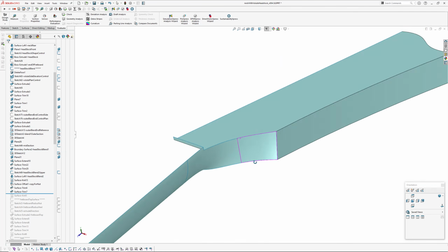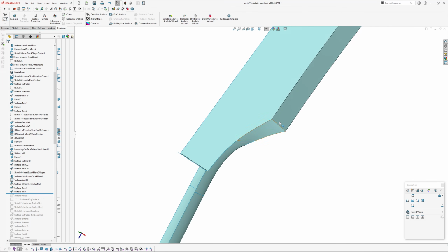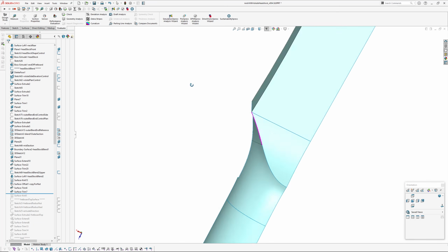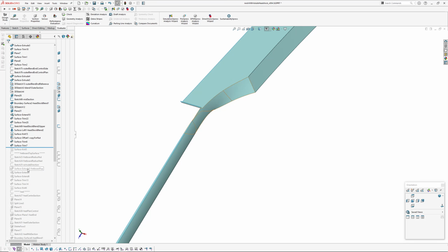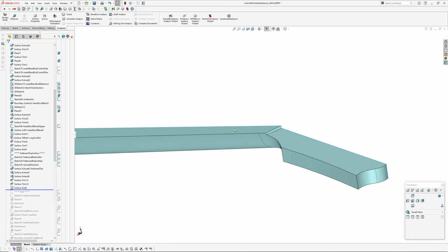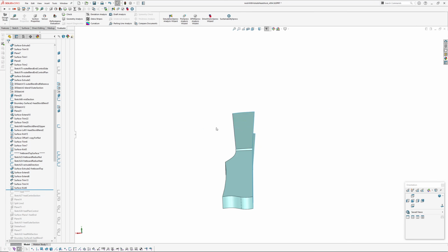Okay, so I'll tweak some of the dimensions in here, because when you look in here on the neck, you want to have this full, but you don't want to have the volute jumping out. Okay, and then that's knitted together. Fretboard top surface. I'm not going to go into this in too much detail. I've covered this in my other video. So it's just some construction there to make the fretboard with a constant radius, even though it's getting wider.